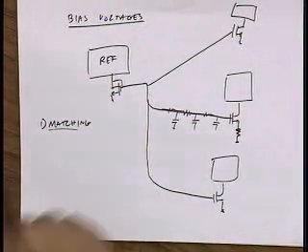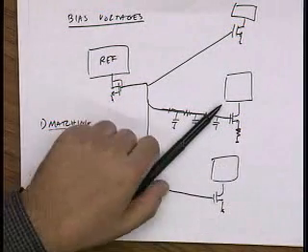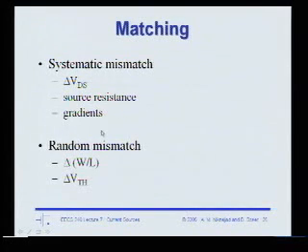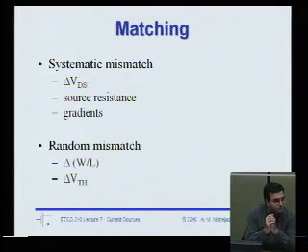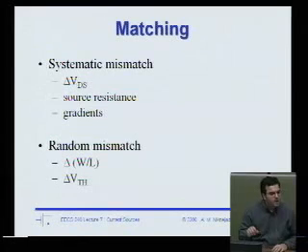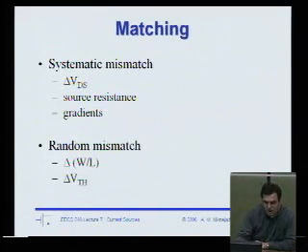Okay, so the other, you might call this systematic. If we go back to the slide, you might call this last thing gradient systematic, or you might say it's random, depending on your perspective. If you're a circuit designer and you've got chips back and the threshold voltage is varying all over the place, it kind of looks random to you. But some process engineer will say, if we make a plot of the threshold voltage, there's contours of constant voltage, and that's because of the way I injected my ions and who knows what. So, okay, more or less it's random.